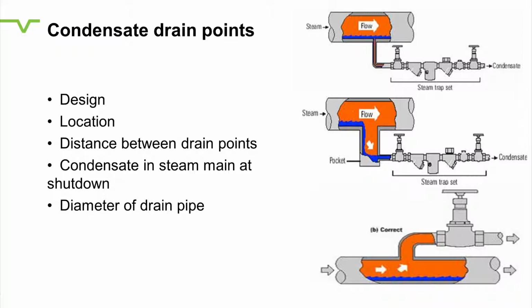It hits that control valve at very high velocity and destroys it. Destroys the pipes, destroys everything. So it's important to stick a decent pocket in the line to drain any condensate out so you don't have that situation. And the photo there shows you the typical drain point and the fact that you should put pockets in there to maintain your systems.